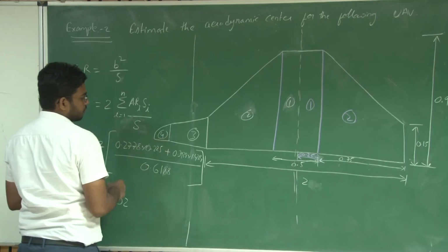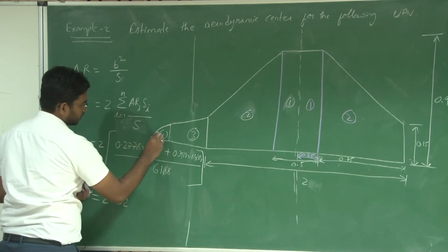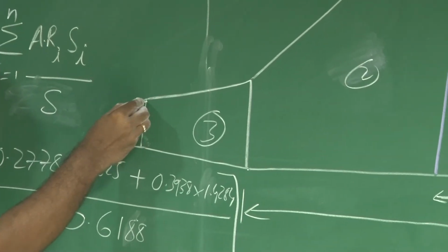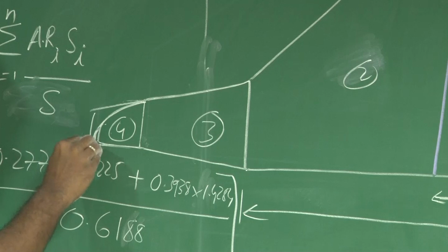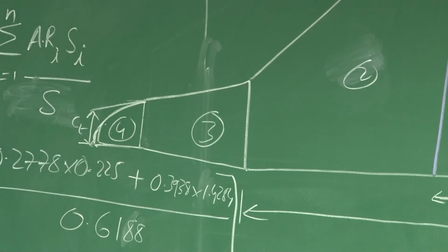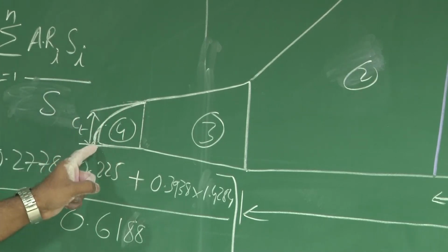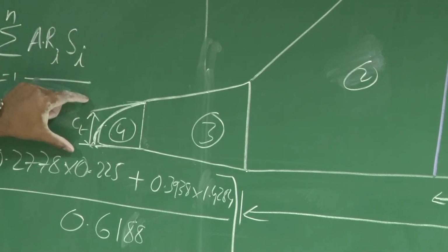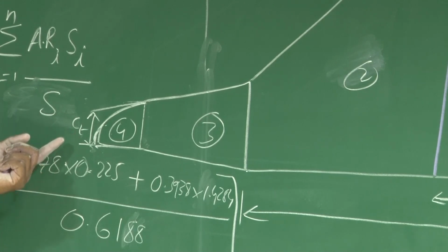Say if you have an elliptic planform like this, you will not be able to find the tip chord here. In that case, you can extend this taper and consider this distance as your tip chord, CT. For an elliptic wing, here the taper ends, and after that you will get an ellipse. So you extend the taper of the adjacent section and find the corresponding length at the tip. This chord length will be the tip chord length for the elliptic wing.